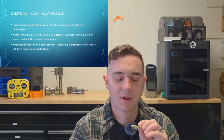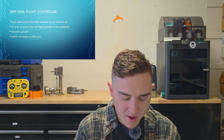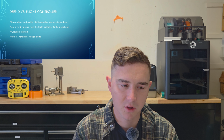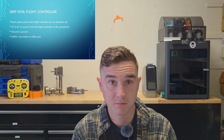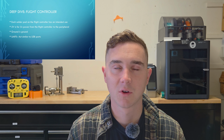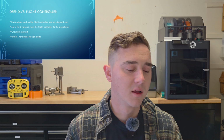We'll get into some of the stuff that I talked about a little bit later, but just flight controller, great. Each solder pad on here is going to have a specific purpose, generally speaking. So 5 volt means it's regulated 5 volts from the ESC to whatever that purpose is. If I have an HD video transmitter that requires 10 volts, and I wire it to a 5 volt pad, as that regulator regulates it at 5 volts, it's not going to power that HD video system.